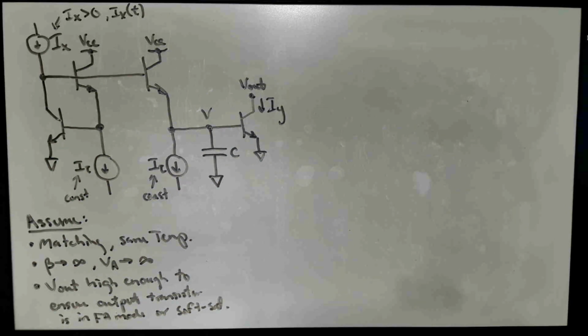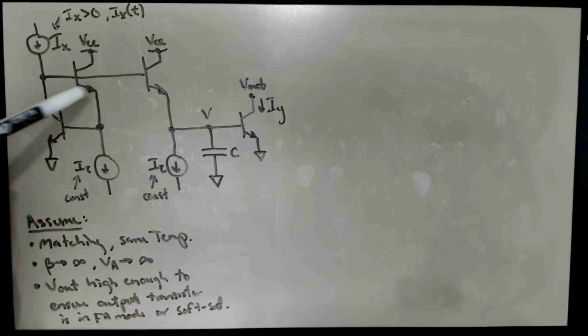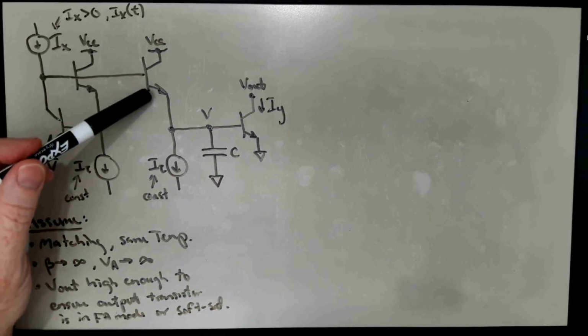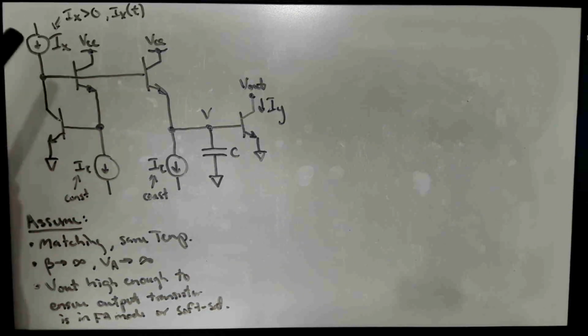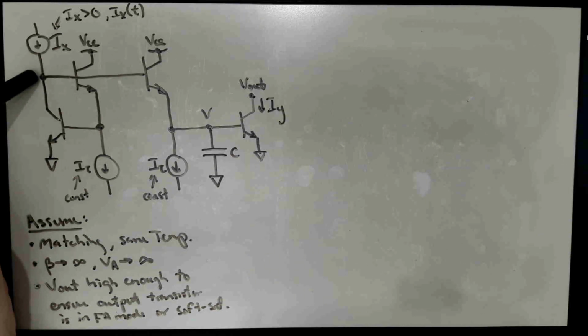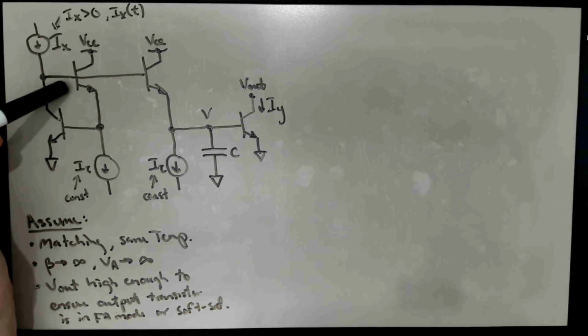Okay, the first thing to do is to think about, well, are these 3 transistors, which we're not guaranteeing are forward active by hypothesis, going to operate in the forward active mode? Well, these 2 transistors are both like emitter followers, as we've been talking about, and the base voltage of them is basically 1-2 VBEs above ground, roughly in the range of maybe 0.8 to 1.4.